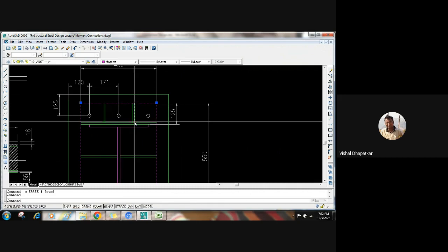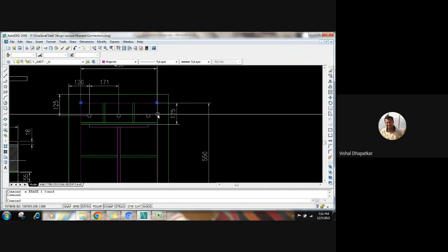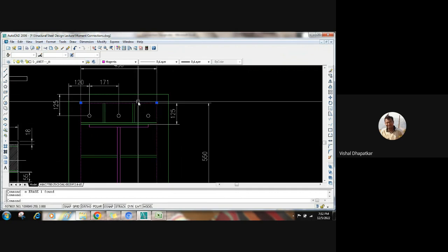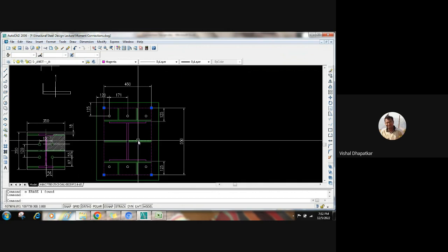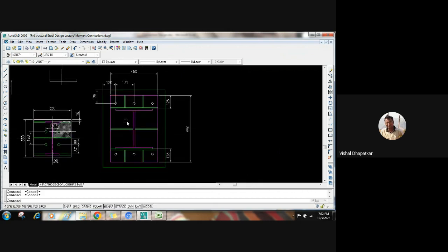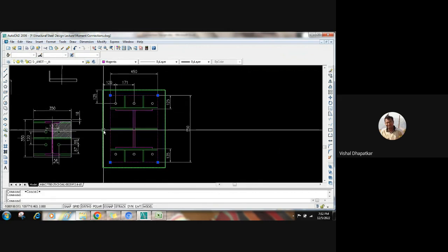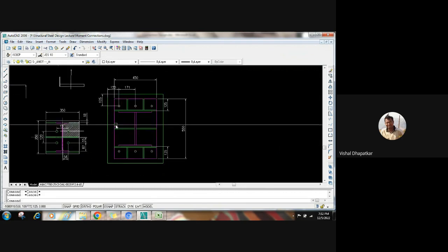Third thickness will be for this corner portion or cantilever portion due to the bearing pressure, and fourth thickness will be due to the tension in the anchor bolt when this plate is fixed on two edges or two edges discontinuous. So out of these four thicknesses, whichever is maximum will be the thickness of the base plate, right? Understood this?